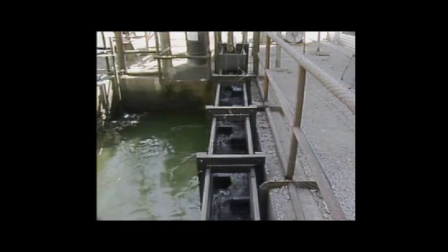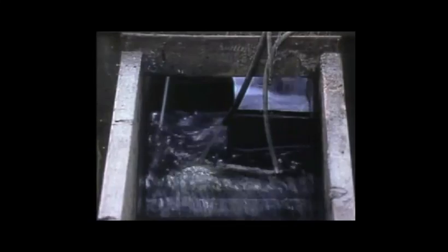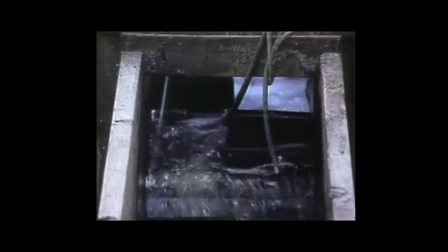To counter the effects of dissolved gases, corrosion inhibitors, such as lime, are often added to interfere with the corrosion process or increase the water's pH. Your cooling system may have specific operating requirements for pH. These requirements will strike a balance between a high pH that will reduce the rate of corrosion and a low pH that will reduce the rate of scale formation.